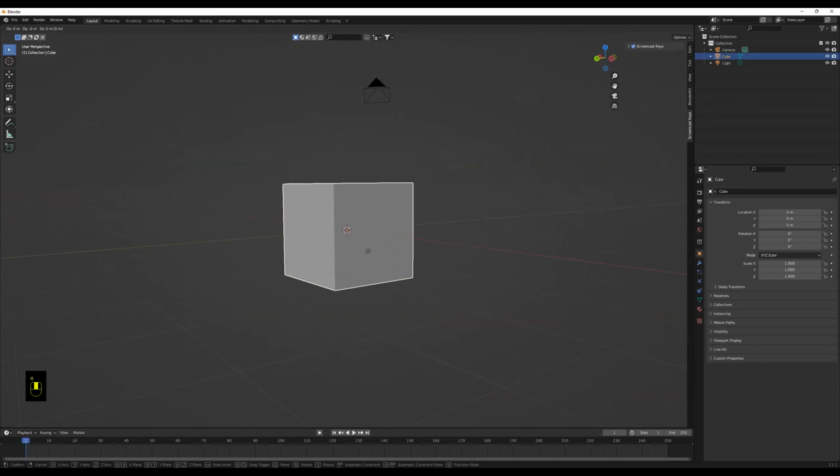I left edit mode, so I have to click back onto my object and press Tab. And we're going to move up here. I'm going to select the top face now because we have to create the hat of our lantern. Once you have the top face selected, make sure it's only the top face. Go back to the view. You're going to extrude up just the tiniest bit, and it should match up with the bottom of the hat on your reference.